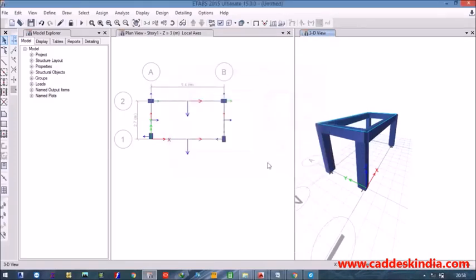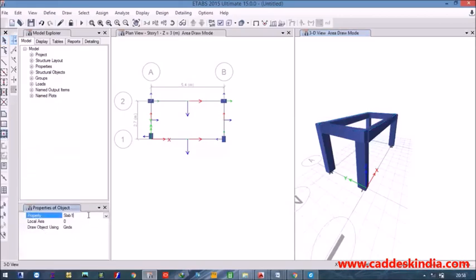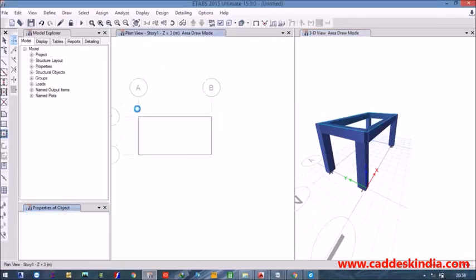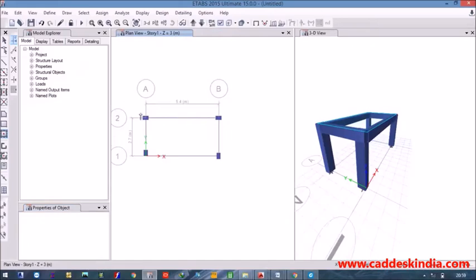Click on OK. After that, on the left hand side you have three options to draw your slab. So you can select the last option, quick draw floor. When you click, similarly it will ask you about the properties. So mention your slab properties. Suppose this is slab 125, and make a slab property by a selection box.